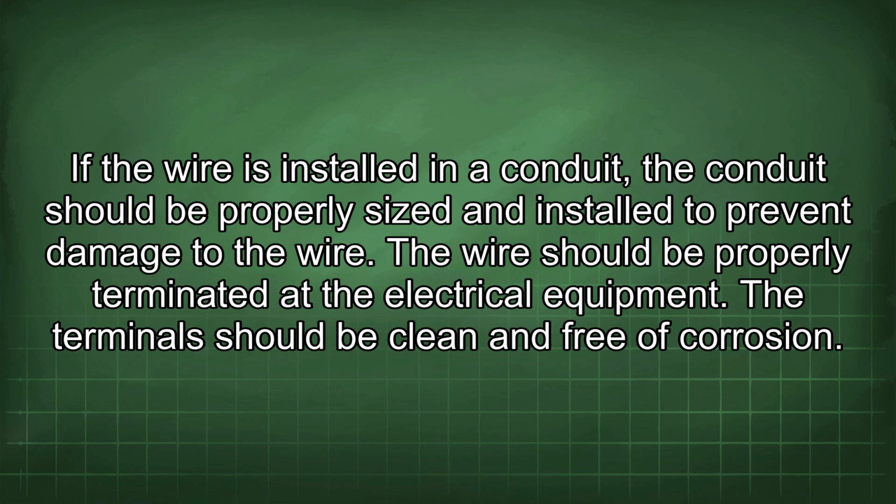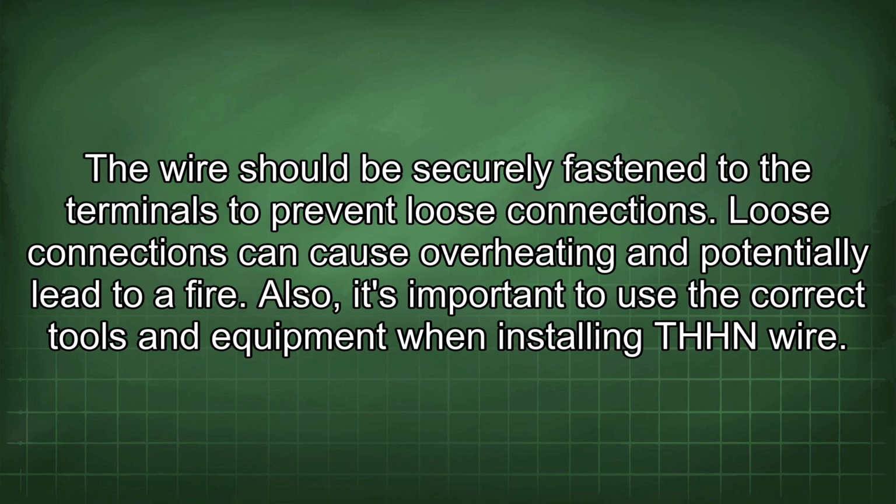The wire should be properly terminated at the electrical equipment. The terminal should be clean and free of corrosion. The wire should be securely fastened to the terminals to prevent loose connections. Loose connections can cause overheating and potentially lead to a fire.